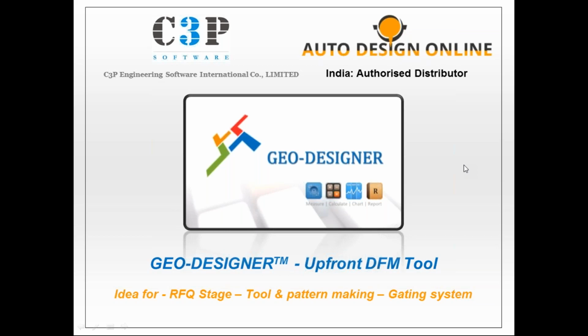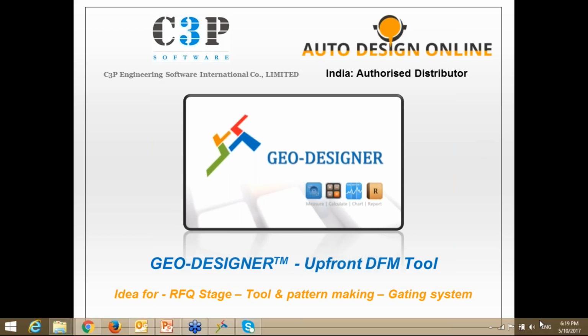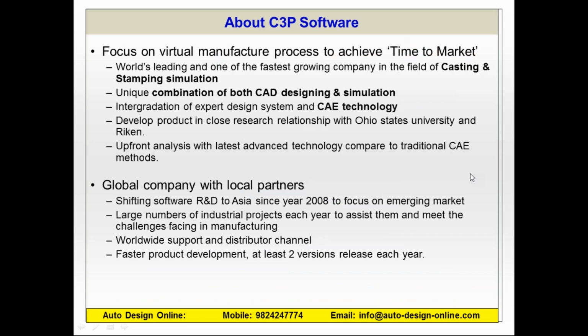So these kinds of questions can be answered by the DFM tool, which is not actually a simulation tool, but will be useful for the designer at the early stage to decide quickly about the gating system, and so forth. Right. So the purpose is how we can do this, the complete requirement of different casting parts and their geometry.